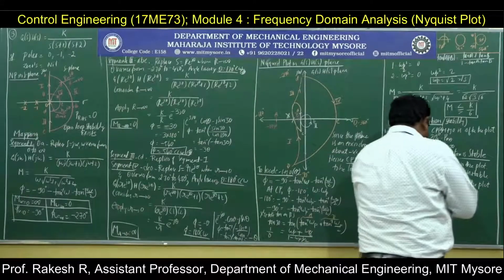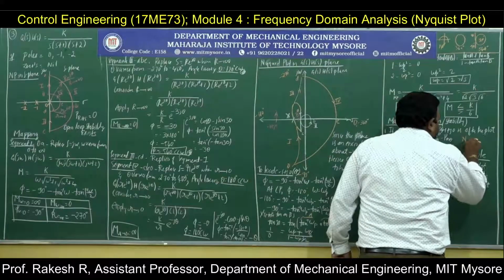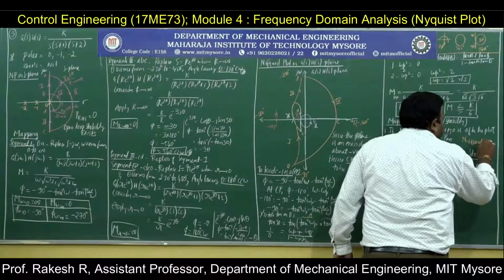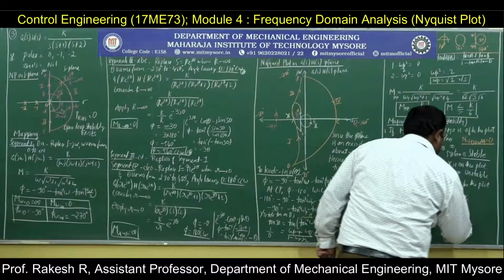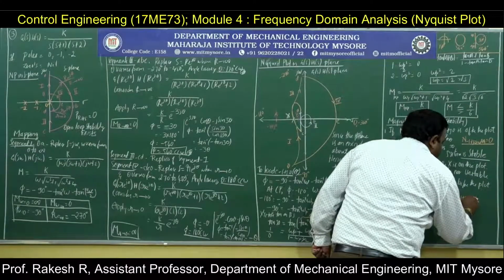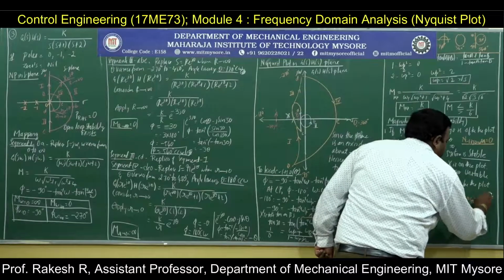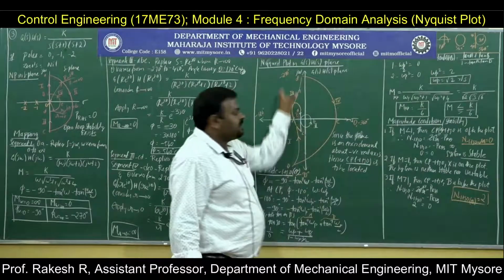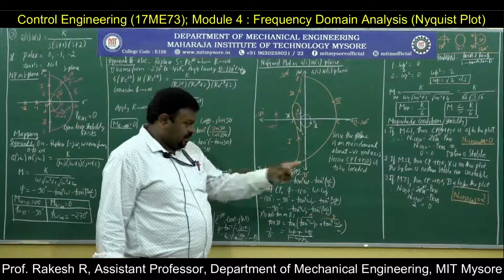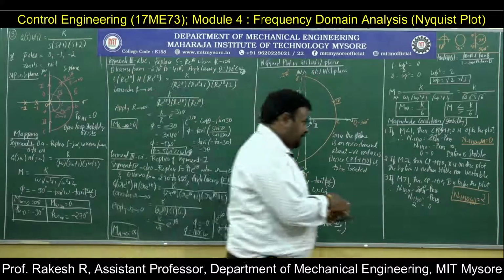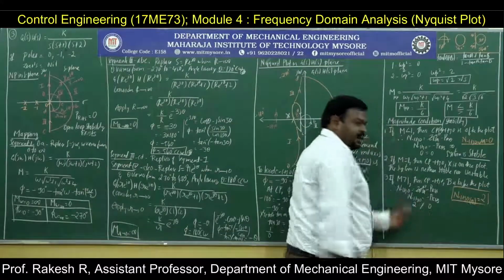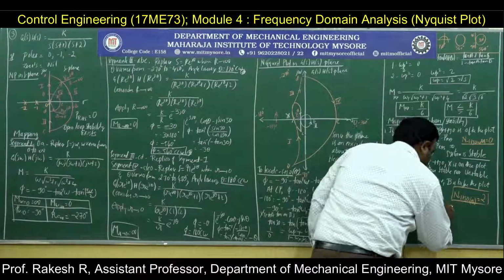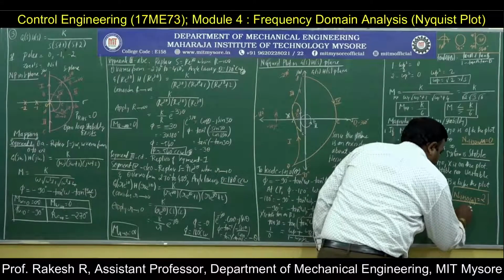So here N minus 1 plus j0 at A is equal to 0. N minus 1 plus j0 at B is equal to 2. You have two encirclements. See here, segment 1 and segment 3. So you got 2, but 2 is not equal to 0. LHS is not equal to RHS. System is unstable.